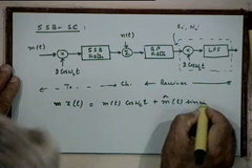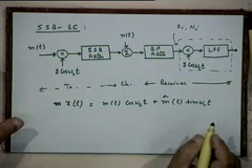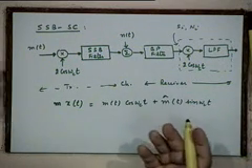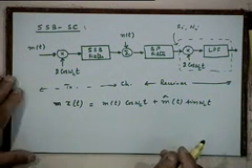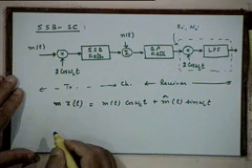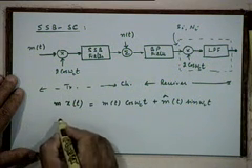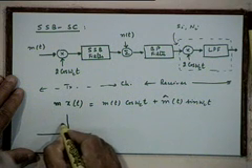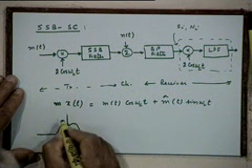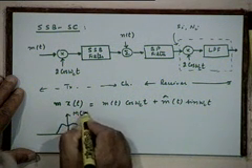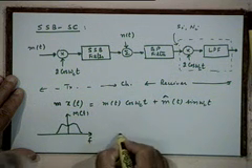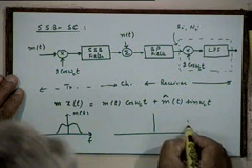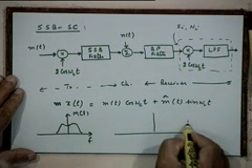Right, where n hat is the Hilbert transform. Whether it will be plus or minus here will depend on whether you have removed the lower sideband or the upper sideband, right. So that doesn't matter. And you remember the spectrum, just to recap, let's say this is your message spectrum, just for the sake of discussion to remind you, your modulated signal would have a spectrum like that.